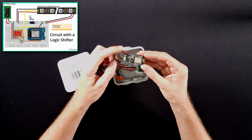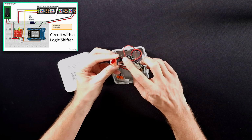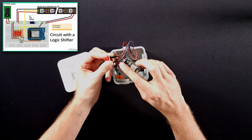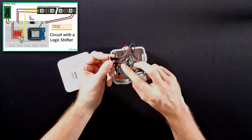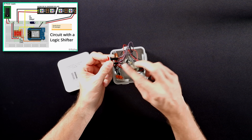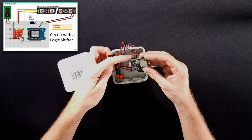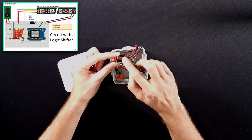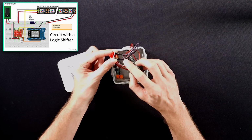So going through the wiring, I've got 3 volts and ground connected to the logic level shifter on one side and also a GPIO pin. And then on the other side, I've got a GPIO pin which goes to the LEDs. And then I've also got a ground again. And I've got a positive here, but instead of being 3.3 volts, this is 5 volts. So this goes to the 5 volts, which is on the controller here under V in. And this is required so that it can tell what the voltage difference is between the two so that it can correctly upsample the data from 3.3 to 5 volts.